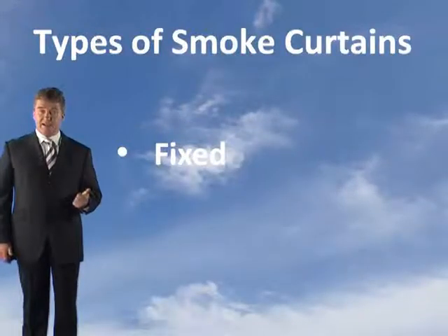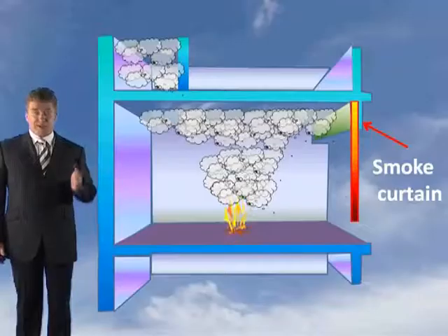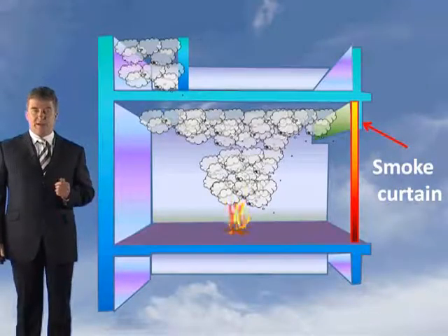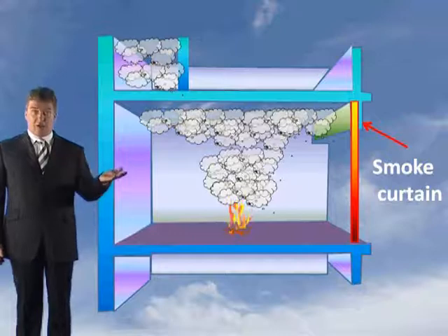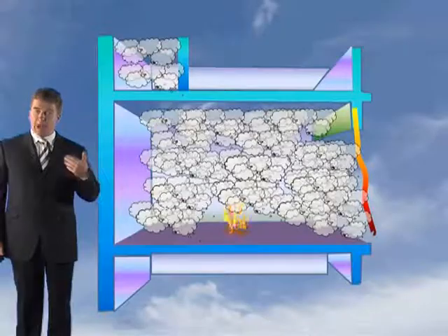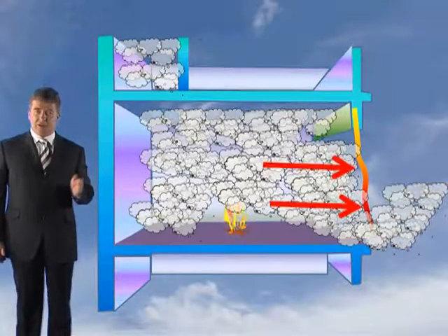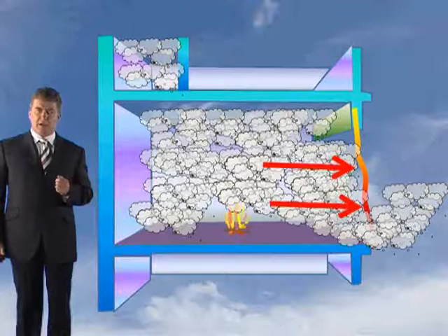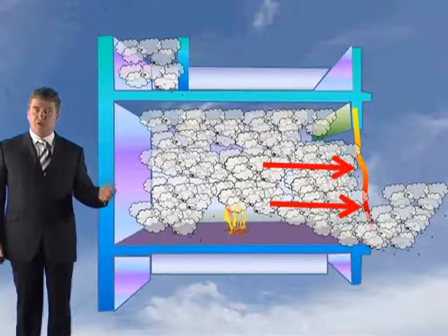Now there are two types of smoke curtains: fixed and movable. Now movable curtains are usually designed to drop vertically in response to an appropriate signal, for example, a smoke alarm or a sprinkler. Setting off an alarm will make the smoke curtain drop. Now where these are not guided by vertical channels, in other words they're free hanging, they have to be long enough to contain the smoky gases without spillage due to the horizontal deflection caused by the hot gases. So it's not flush, they've got to be longer than this. And again, as I said before, the fan-induced pressure differentials caused by the exhaust fans.